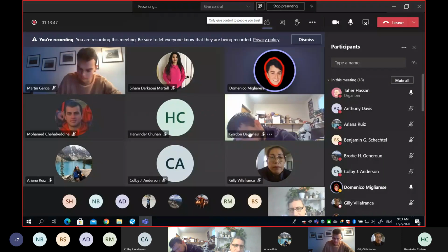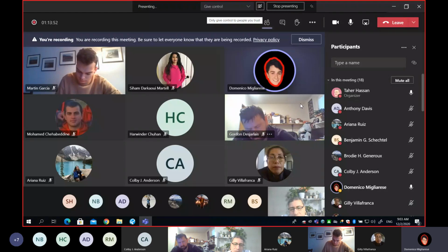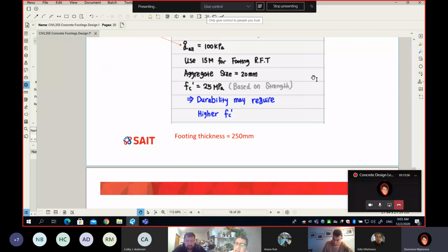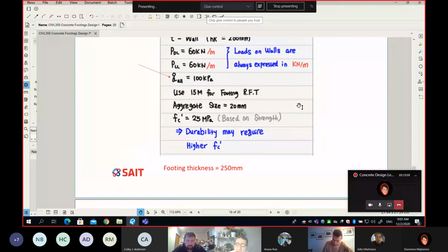If there's sulfate in the ground, why wouldn't we use a different specialty concrete instead of upping the MPa? We do the same. The code, when you have sulfate exposure, let's say high sulfate or medium sulfate or severe sulfate, is not only asking for one, you have to do both. You have to use a kind of cement which is sulfate resistant, and also increase the f'c. Both of them, not only one, sir. Okay. What about admixtures, like corrosion inhibitors?